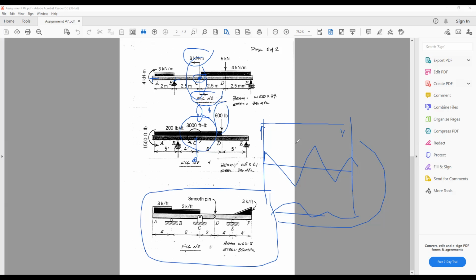Okay, so I don't know if you guys have started on these assignments before the second lecture, but if you have, I mean. I have a question. Yeah, go ahead. Yeah, so we see the size of the beam. So let's say W250 by 39. The steel, because it doesn't calculate unless you give material to the beam. So what is 350 MPa steel in the list? Okay, so I'll show you where that is.